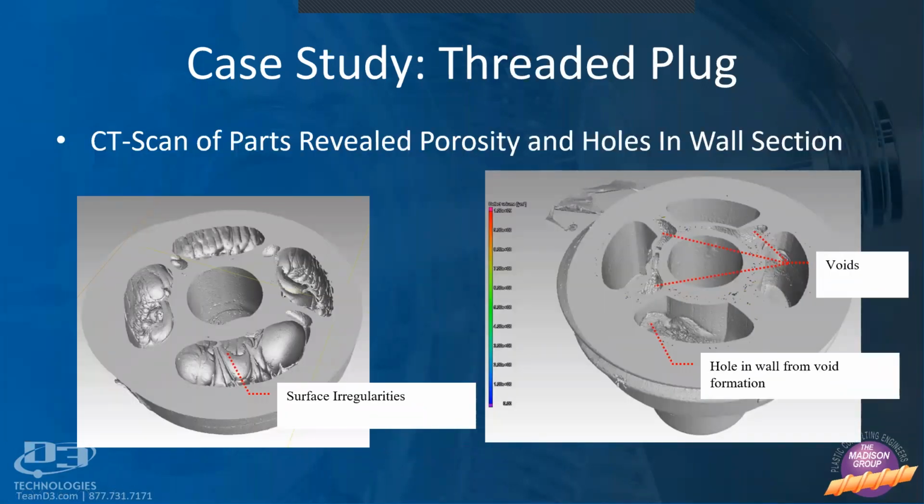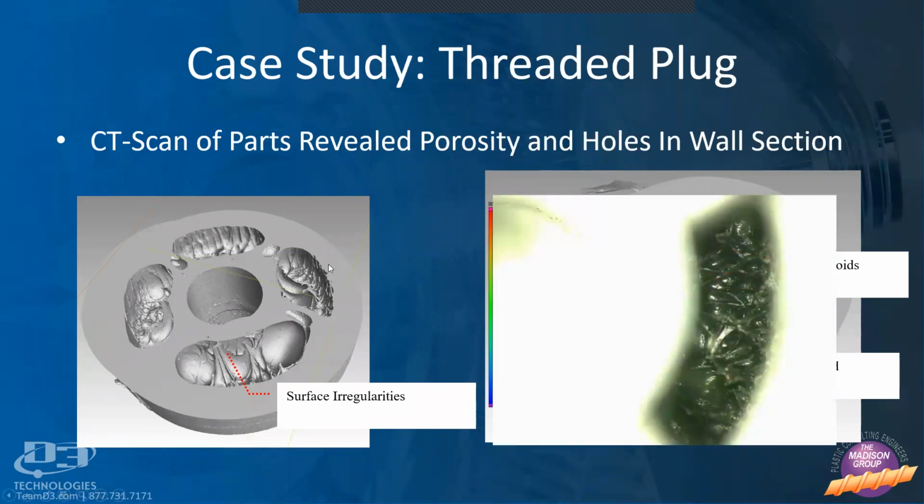And so when we look at how that influenced our part performance, we were running those tips so hot that the material wasn't even setting up and the material was bubbling at the surface, and we saw a lot of poor surface aesthetics on our molded part, and even some porosity in our part. You can see that we don't even develop a full wall where we need the structural integrity for our part. And so this is going to weaken the part by not having that ideal cooling. And again, we can see on this mold on the actual part, we can see that we have a rough surface here at the base of those cores.